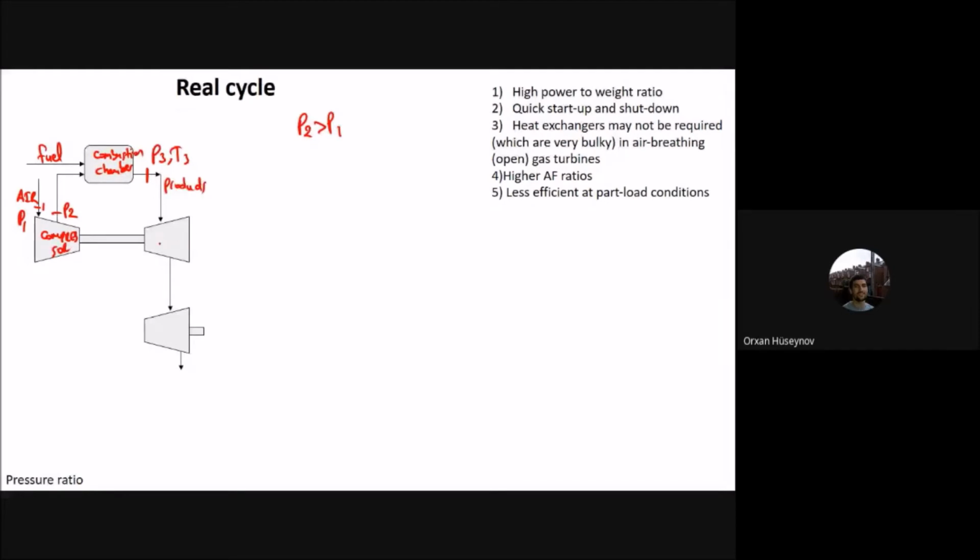Okay, here you have two turbines. There is the compressor, and you have turbine 1. This turbine 1 is called the gasifier turbine. You can see this gasifier turbine is connected to the compressor with the same shaft. What it means is that whatever power you get from this gasifier turbine is used for the compressor, because you know from thermodynamics 1 that the compressor needs work done in, and this gasifier turbine gives you work done out. This work done out is used to power the compressor, and therefore you can see the shaft. This shaft is coupled with the turbine and the compressor, and therefore whatever power you get from the turbine is used for the compressor.